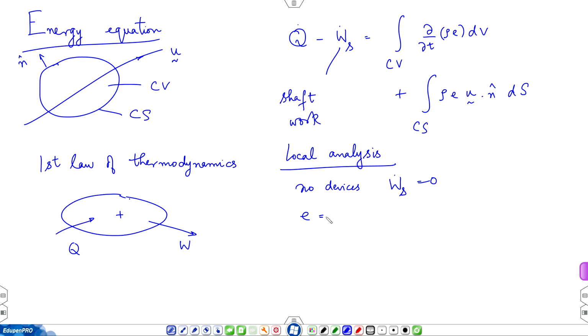The definition of total energy is I plus P over rho plus U square over 2 plus G z. Okay. Now, this I plus P over rho is often called enthalpy and is written as specific heat times temperature for most fluids of the type that we have considered in the first part of this course, where we had air, water, oils.